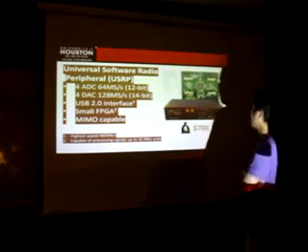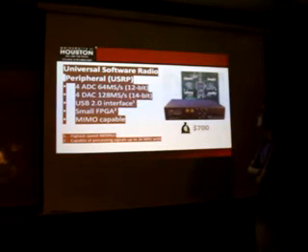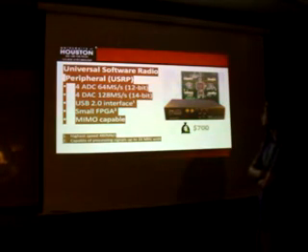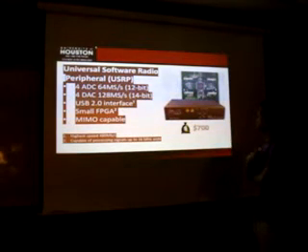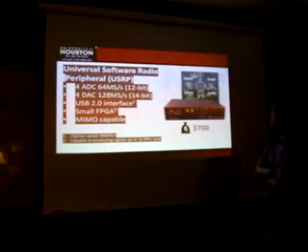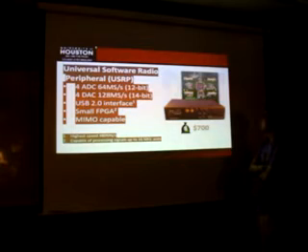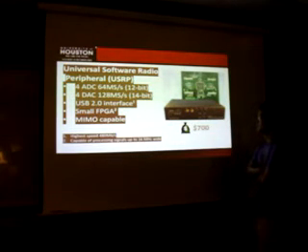Here is the hardware of the USRP1. USRP1 has 4 ADC and 4 DAC, and it uses a USB 2.0 interface to communicate with the computer. It has a small FPGA in it, and it supports MIMO. The price of the USRP1 is $700.